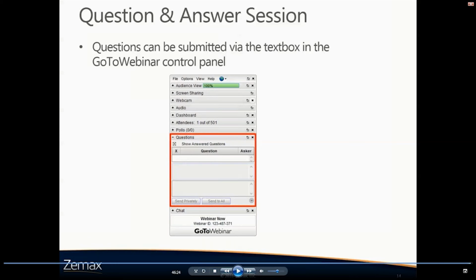Question number one was, what is the best built-in scatter model for a ground glass surface where rays are scattered both into the material and out of the material? I think that most of the time, what I've seen commonly used in that scenario would be a Lambertian scatter profile.